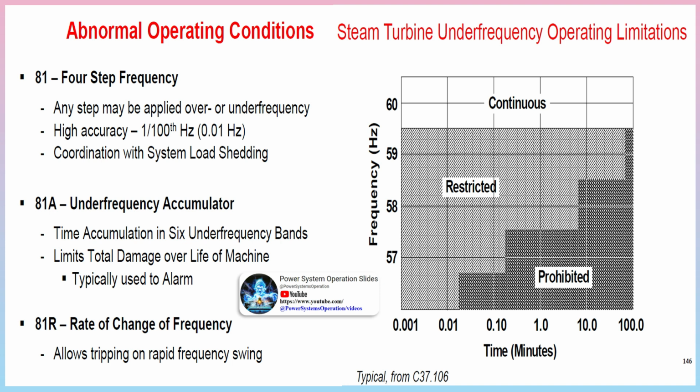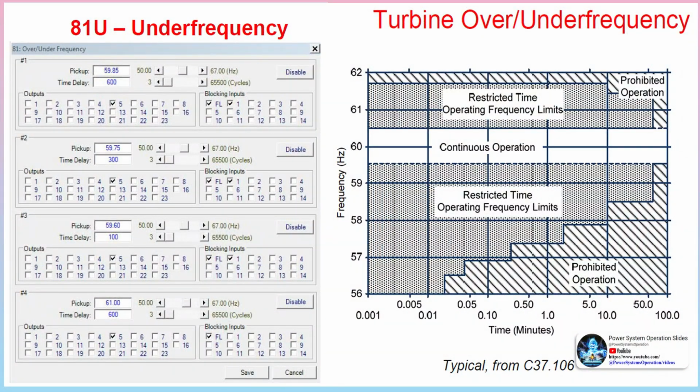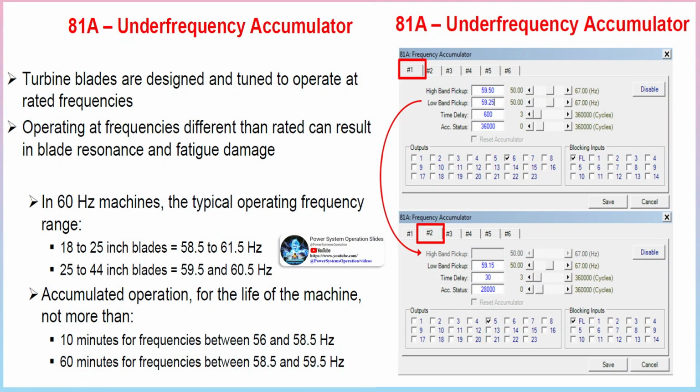This protection usually is in the form of a regulator which compares the vacuum against atmospheric pressure. It is normally fitted to the generator set above 30 megawatts. The modern practice is for the regulator to unload the set via the secondary governor until normal vacuum conditions are restored. If the vacuum conditions do not improve below 21 inch, the stop valves are closed and the main circuit breaker is tripped. Protection against lubrication oil failure.